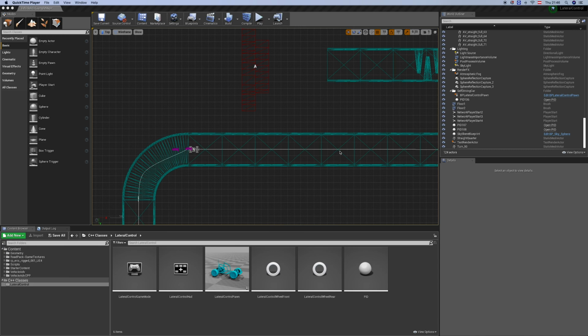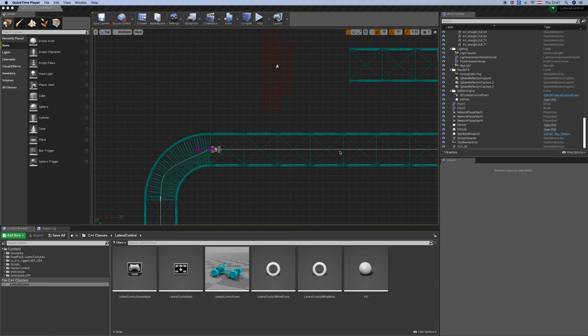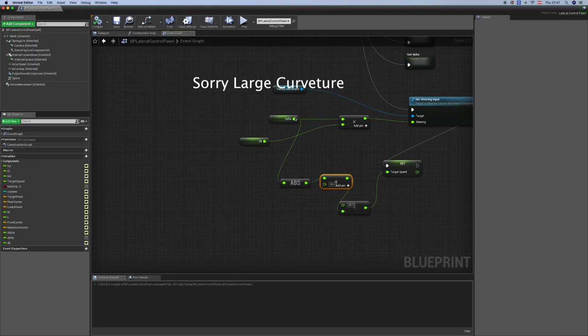And the question now, can we also control the speed with respect to the path or the curvature of that spline? And the answer is yes. What we'll do now is adaptive speed control, where the target speed would be calculated with respect to the spline curvature. And actually what we will use here is the angle that we are calculating, which is a delta angle. Because if we have a large angle, that means we have a large radius, and that means we need to slow it down. And if we have a straight path, then we can speed up.